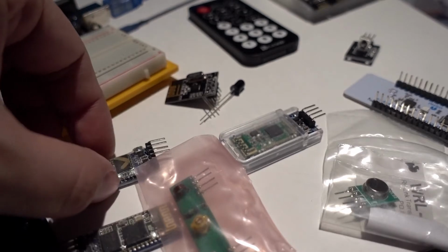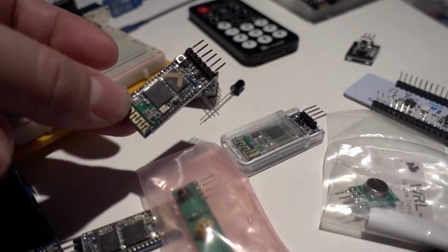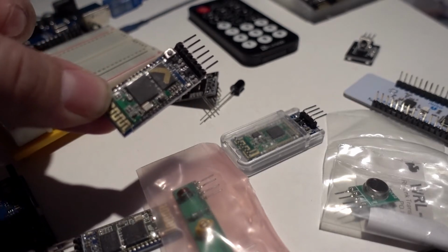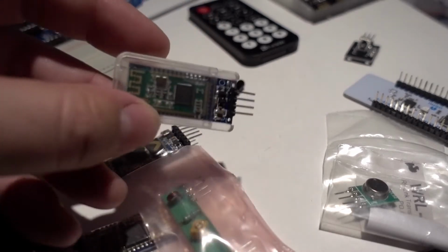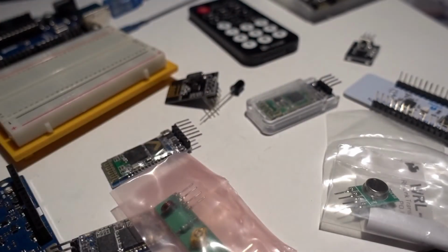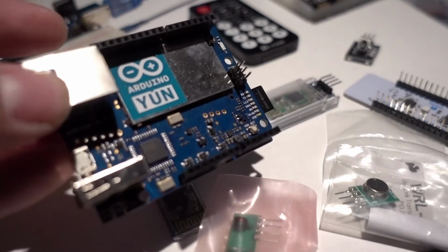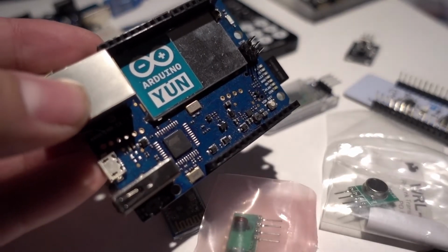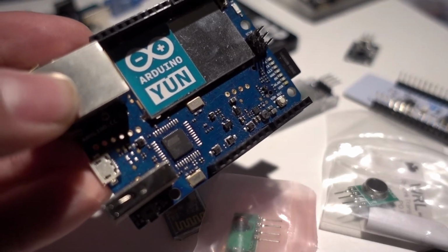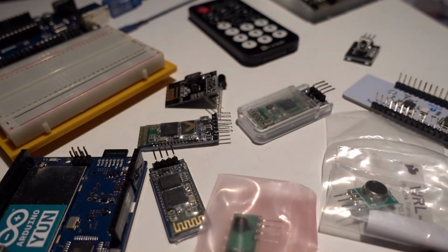And then there's Bluetooth, and there's several options for Bluetooth. There's a Bluetooth which essentially is just like the serial communications we've been using, but wirelessly. And then there's Bluetooth low energy, Bluetooth 4. There's a lot of options with those, and if you want to use an iOS device, then Bluetooth low energy is the one that you're going to need to use. And then we did mention Wi-Fi. This is the Arduino Uno, which was the first Arduino board with Wi-Fi built in, but obviously there's a whole host of options now.